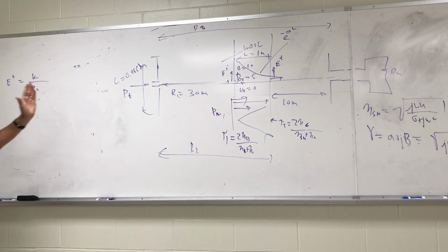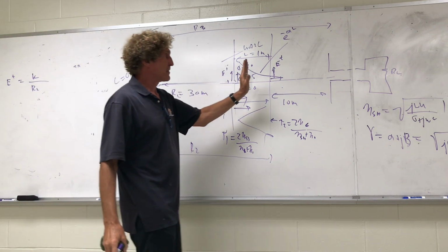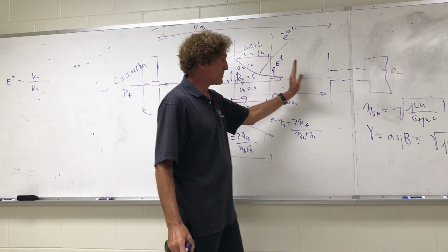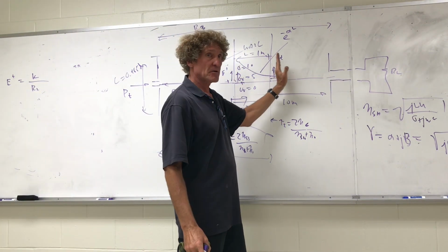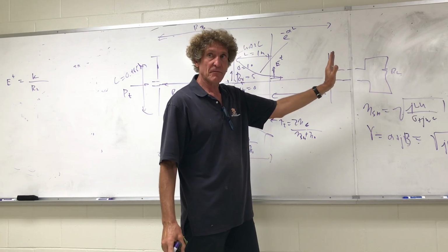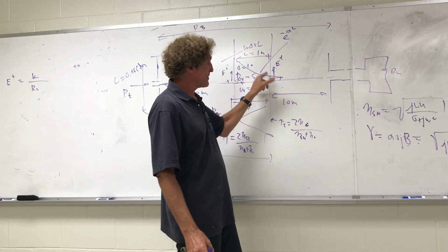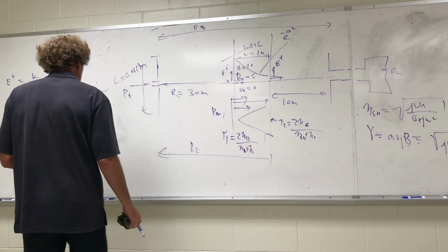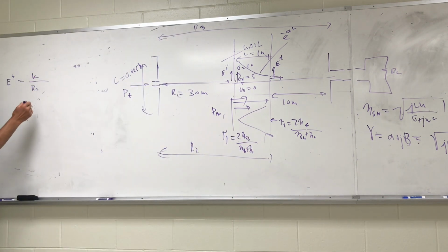Here's what I'm really saying. You're assuming as this is going out, the reduction in the field value after that point is going to be like a spherical wave that normally falls off as 1 over R. So if you know the value here, and that is at a range of R2, you can say K over R2 is the transmitted field value. That means you can say that K itself is going to be R2 times the actual transmitted field value.